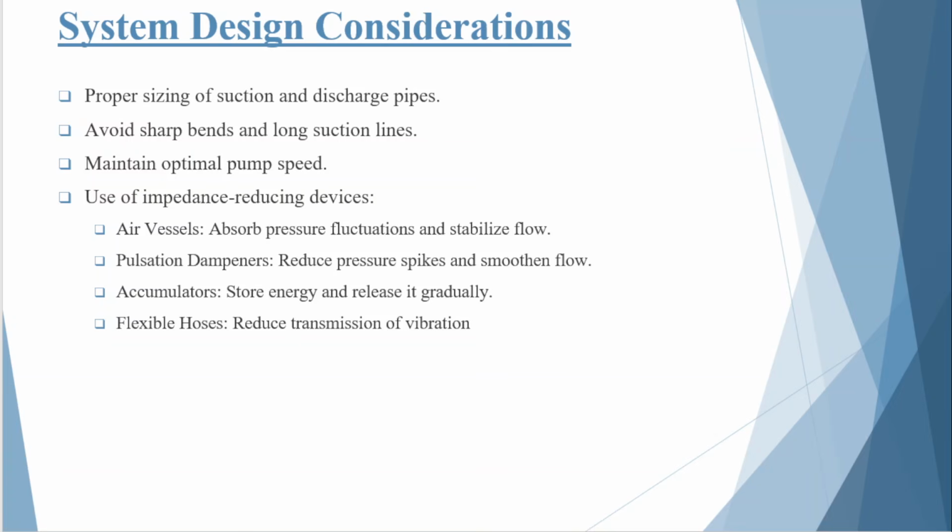The second consideration is pipe length. Remember that acceleration head depends on the mass of liquid inside the pipe. Longer pipes contain more liquid, which means more mass must be accelerated during every stroke. Therefore, wherever possible, engineers keep the suction piping short and direct.